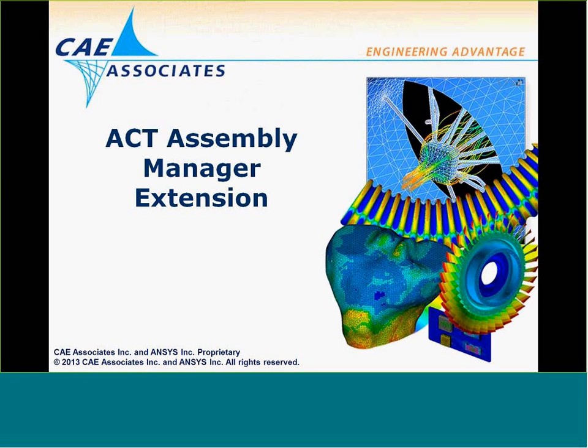Okay, so that is the situation where you have a legacy mesh, again, something that came from the MAPDL or classic environment, and you needed to get that into Workbench. Now let's take a different approach. Let's say we may have multiple Workbench users, and what we'd like to do is combine those Workbench models into one single assembly inside Workbench. Now that will be done using the ACT Assembly Manager extension.